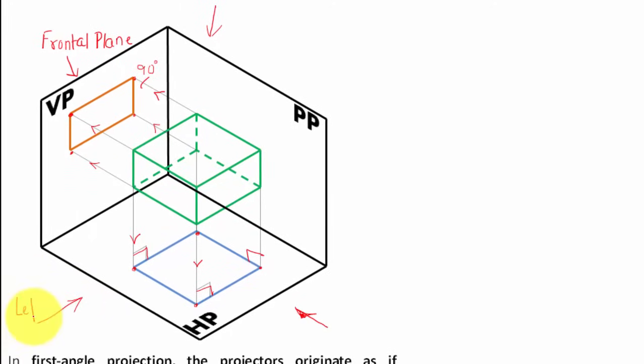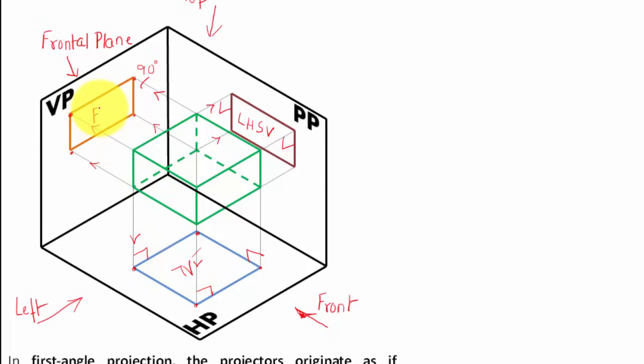So this is left, you can write this, and this was about having the front view, so we had to look at this object from the front, and this was for top. Alright, now let's take a look at this object from the side this way, and hence we are having this. These are the projectors, parallel projectors, and this is the 90-degree angle. Alright, and we have a view, and in this case we are having a left hand side view. This over here represented top view, and this was all about front view.